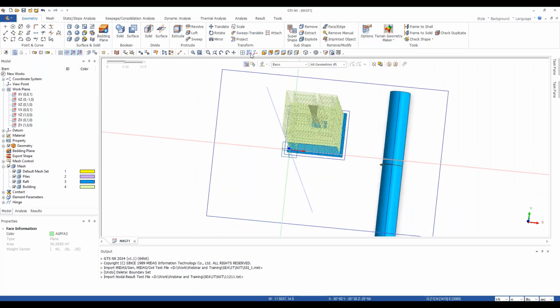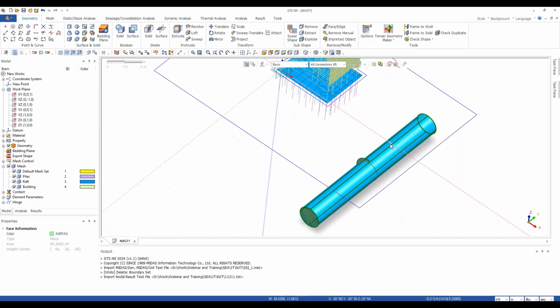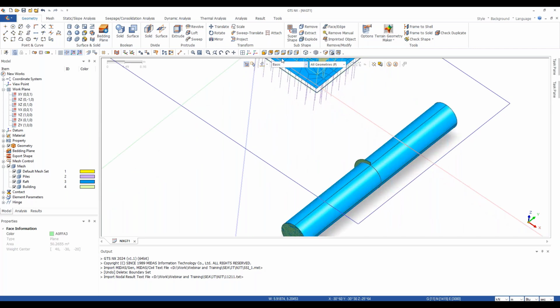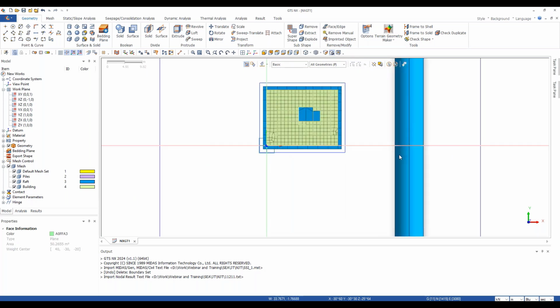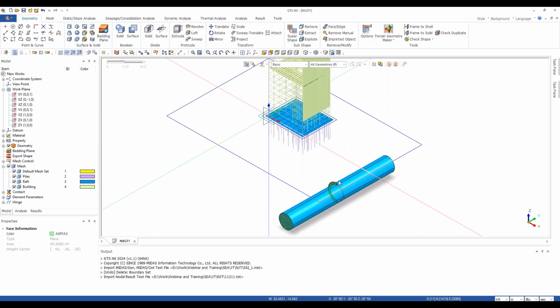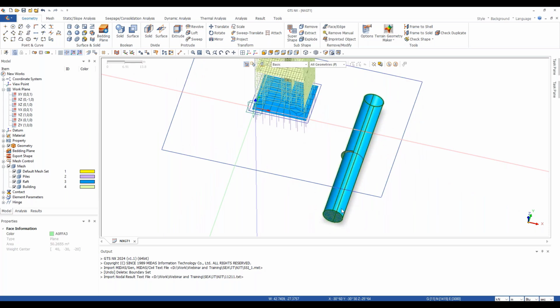Okay. What we will do now is also create the solid volume for the grouting. If you see here, grout starts somewhere here, but in actual, grouting would start much earlier than the zone where your building starts. Okay. Before I do that, we will divide this solid, and I'll explain so that it will help us in moving this grout geometry as well.